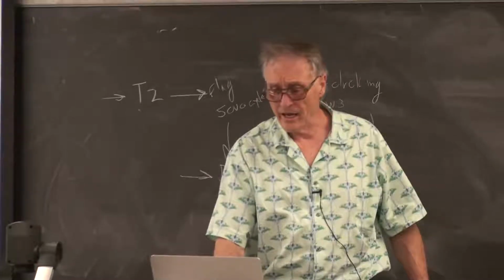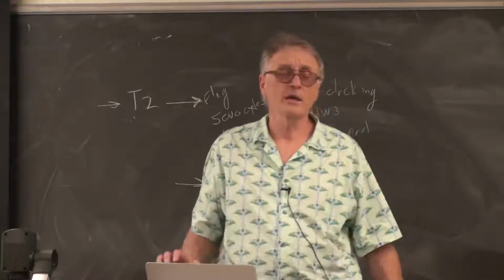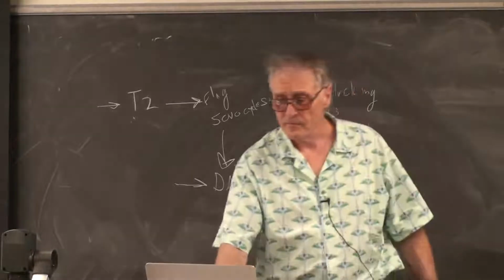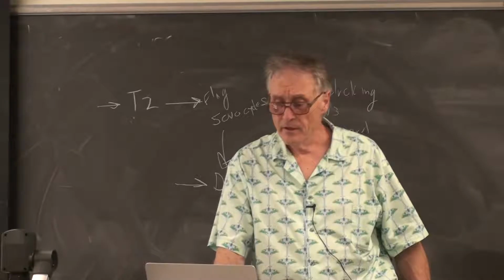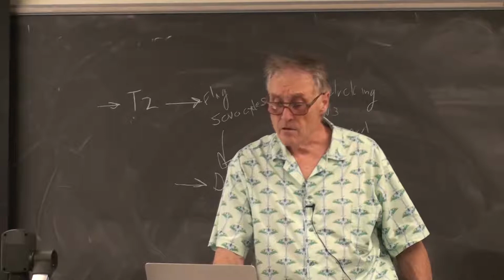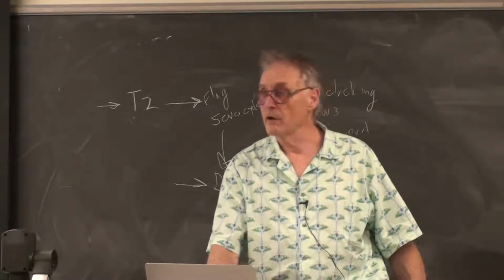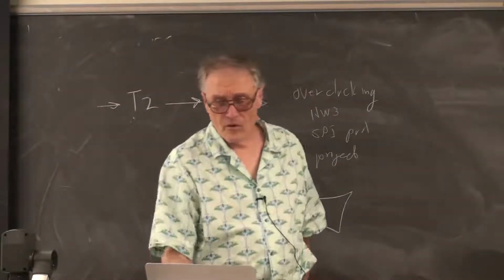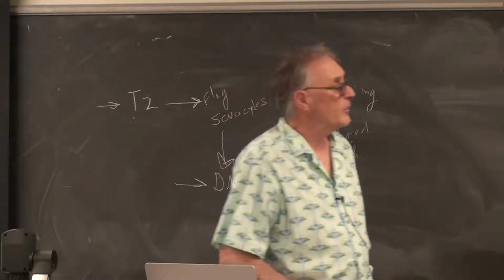We're defining an unsigned char sine table. This is chars because I'm sending 8 bits to an 8-bit DAC. And then setting up the DMA channel. Notice I'm opening timer 2 here, but I'm not turning on the interrupt. No interrupt turned on. Then we open the channel. I opened it in auto mode.